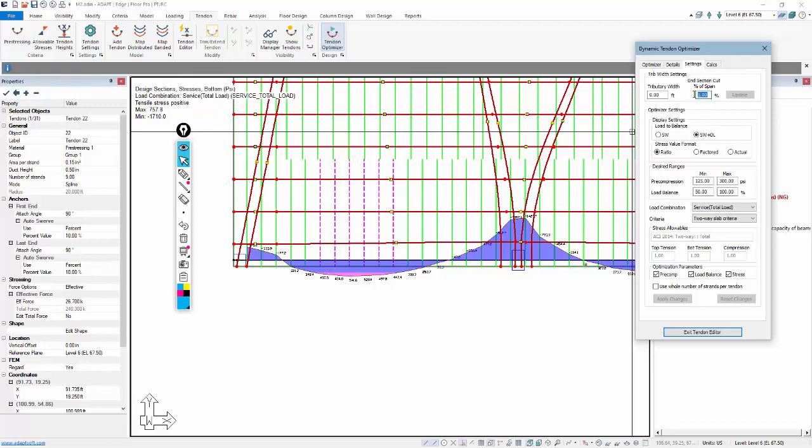We're going to make sure we set these values up based on our design parameters. So we're going to leave these really as they are. Everything here is set kind of to what we want to begin with. So we'll leave these as they are. It's important that the user kind of understands the inputs here, what load balancing we want to use, self-weight plus dead load.